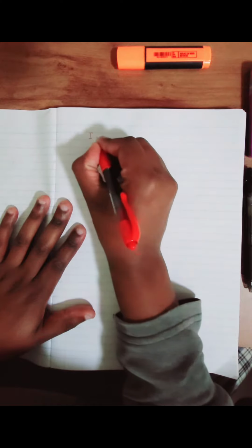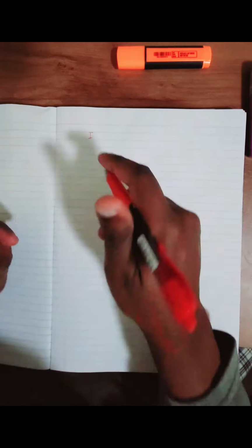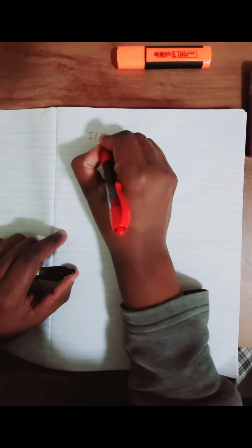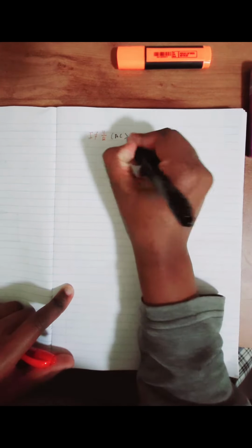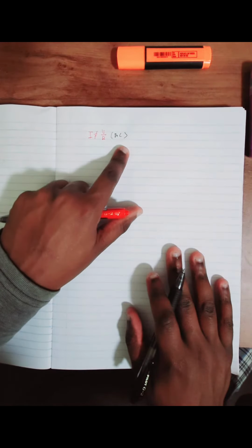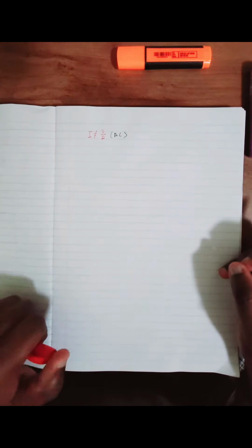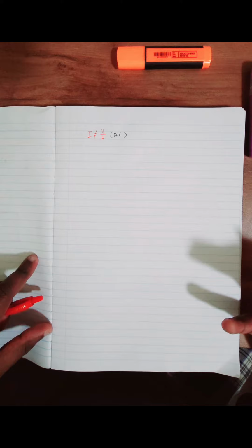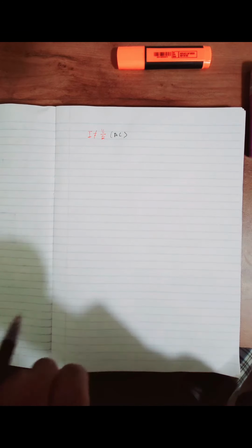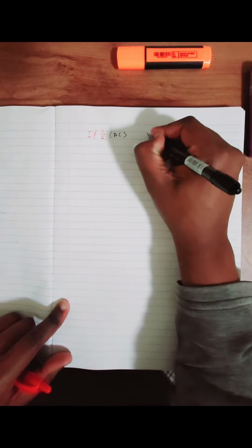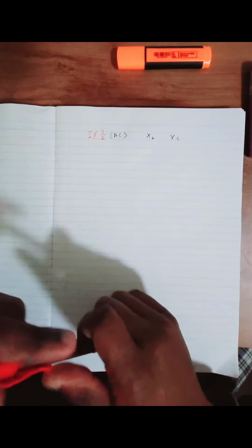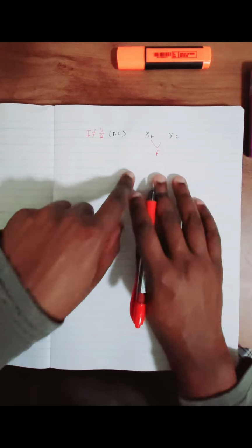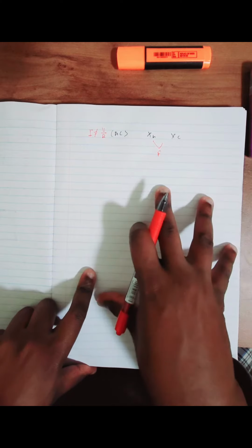Ohm's law in a DC circuit, guys. What I wanted to say is that in an AC circuit, Ohm's law cannot be defined as V over R. That is in an AC circuit where the source is an AC, because with an AC we have to take into account other forms of opposition to current, which are the inductive reactance and the capacitive reactance, because both these values are dependent on frequency, as you'll see as I'm explaining in this video.